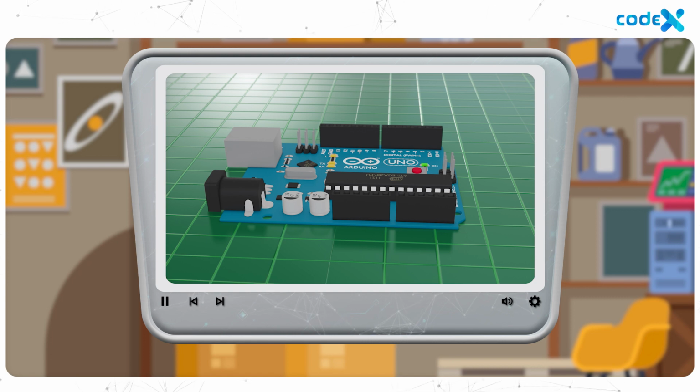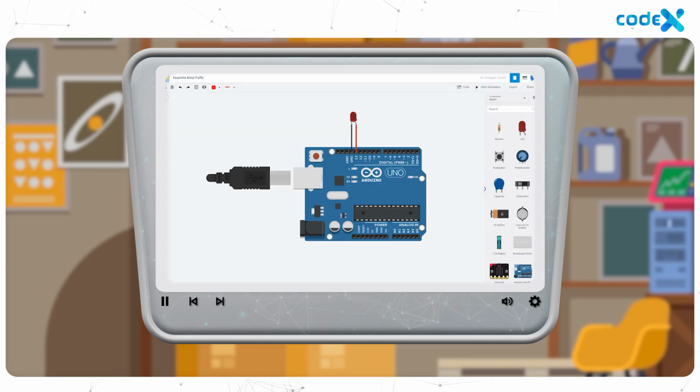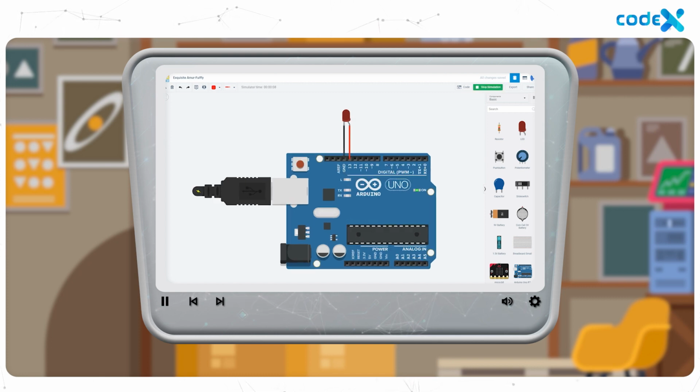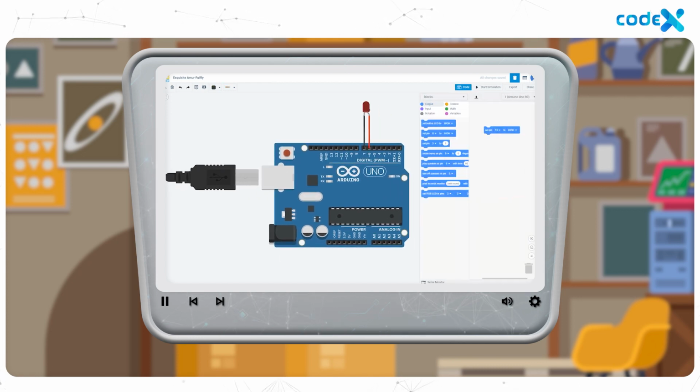We also studied the different pinouts in the Arduino in detail, and we saw how to interface an LED with an Arduino and to turn an LED on by connecting it to the different pins in the Arduino. When the LED is connected to the digital pins of the Arduino, we saw that they won't work until precise coding is performed. We then concluded that coding determines the output in Arduino, and we saw how to change the coding when connections are changed.